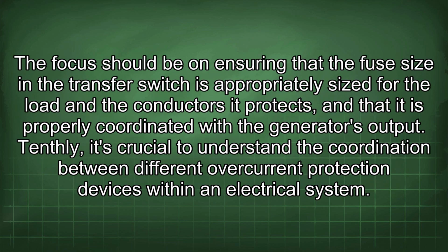The focus should be on ensuring that the fuse size in the transfer switch is appropriately sized for the load and the conductors it protects, and that it is properly coordinated with the generator's output. Tenthly, it's crucial to understand the coordination between different overcurrent protection devices within an electrical system.